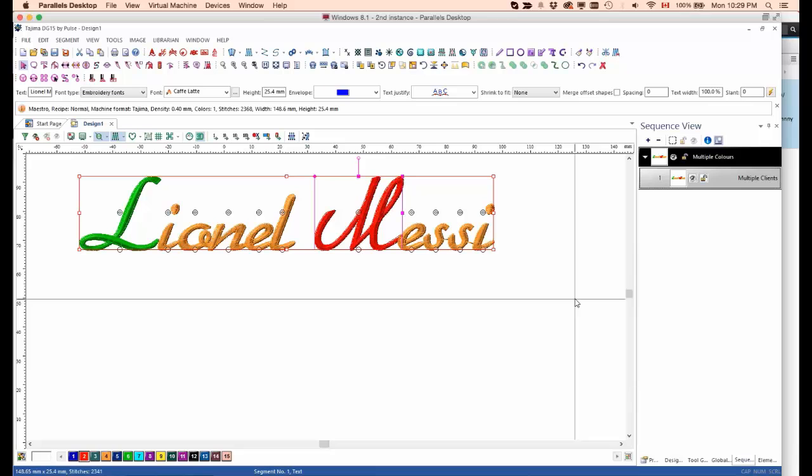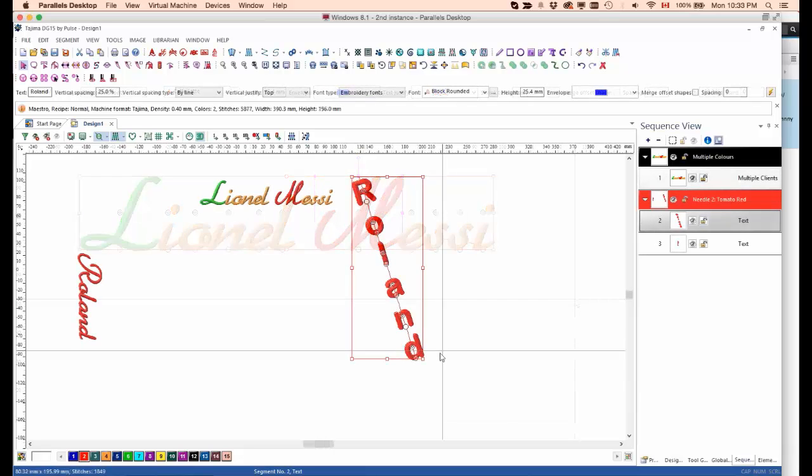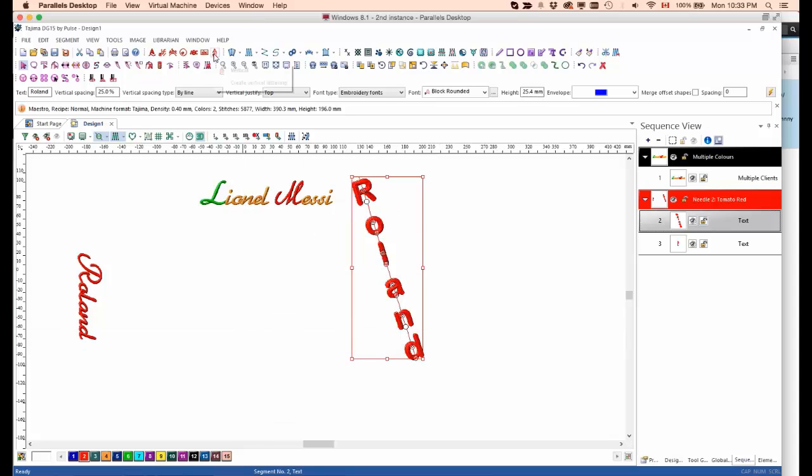Before we move, I have a couple of questions actually. The first one related to the horizontal and vertical text is why, when you click on an angle, the text is horizontal? I would say, with the new vertical text tool, each one of the letters will always be positioned at a 90-degree angle towards the 2 points that you are entering. For example, you see here I placed point A and point B at a little angle. It's not really 90 degrees, but each one of the letters is exactly 90 degrees positioned towards that line.